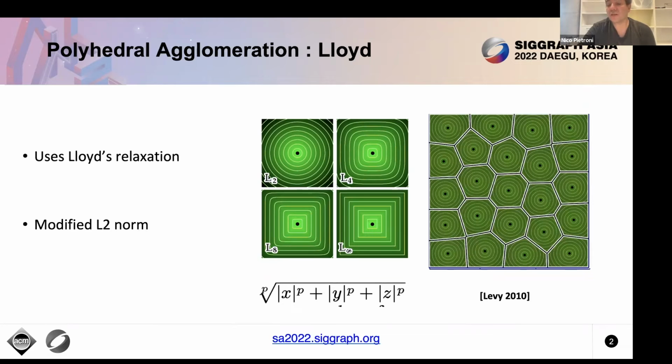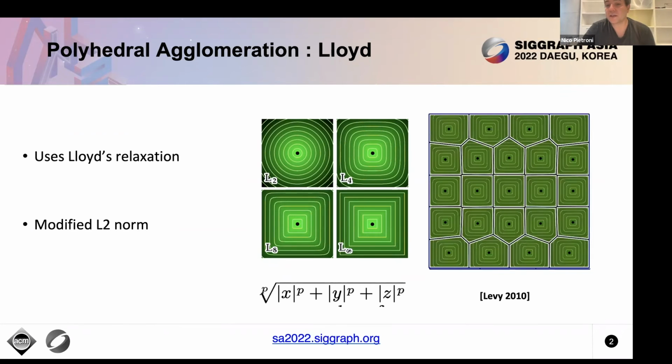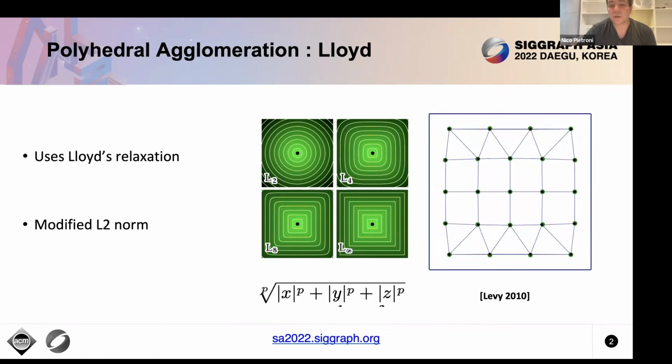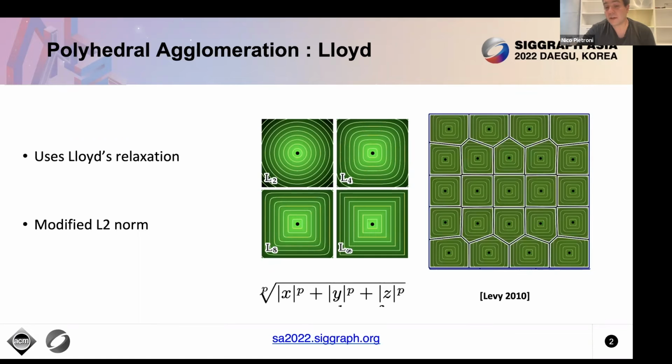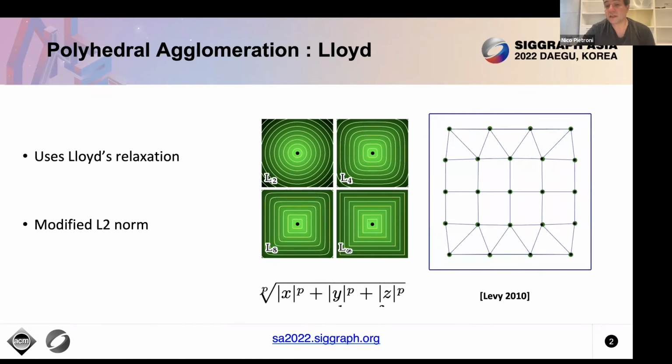So then if you do so, you start from this distance, and you can end up with that. And obviously, you may guess that this is a very powerful tool that you can use in 2D and almost immediately translate to 3D without any problem, because you can immediately create hexahedral cells. And obviously, when you have this complex here, you can take the dual of that and you can have your hexahedral dominant mesh. Obviously, it's dominant because that doesn't guarantee that you have all your cells hexahedral. You still insert some general polygonal mesh.